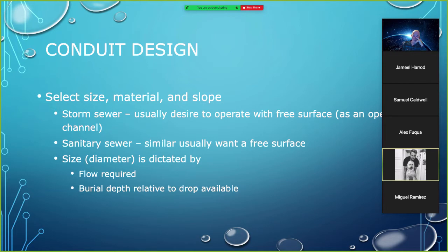Because one of the added bonus features of wastewater is that under low oxygen conditions as they're encountered in a sewer, they can generate sulfuric acids and slowly damage the cementitious materials that hold a concrete pipe together, and then you get the ultimate failure of the system at some point in the future, and it doesn't fail at any place that's nice and convenient.